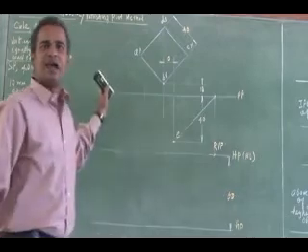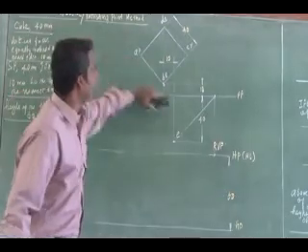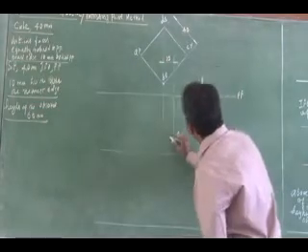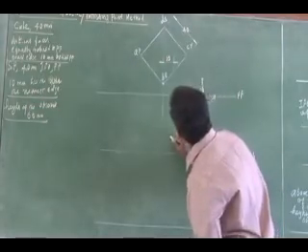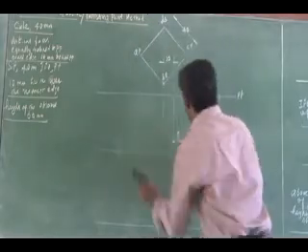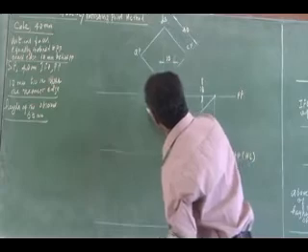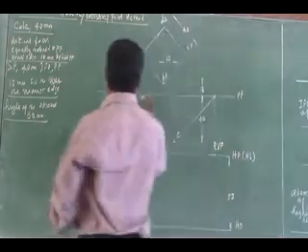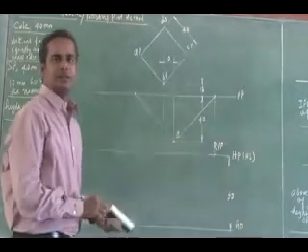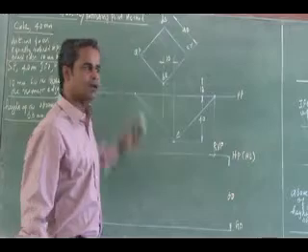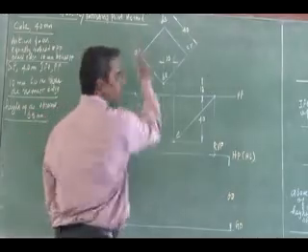Similarly, I can get a left vanishing point parallel to the face BQAP. From the station point, I am drawing a parallel line to face BQAP. Right, this is parallel to the left face, that is BQAP.